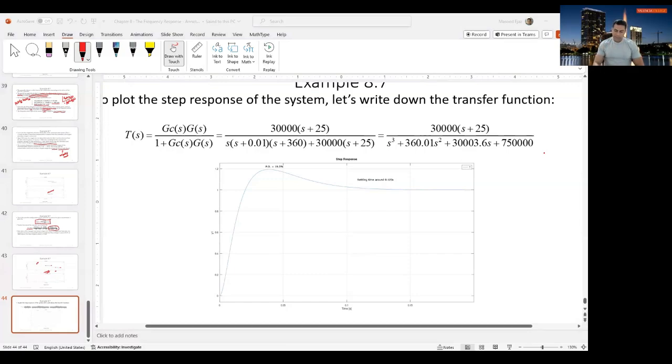So when we do that, we can check what is the time constant of the circuit. But from the graph, we can see that it settled down pretty much to the steady state value between 0.1 second and 0.15 seconds. So the time constant is somewhere in between. I just put the center value, 0.125 seconds. But it can be smaller than that, of course, based on what is the value of 4 time constants.